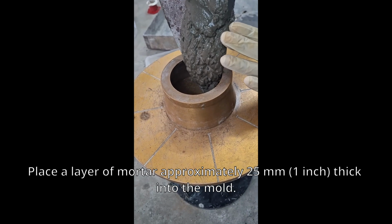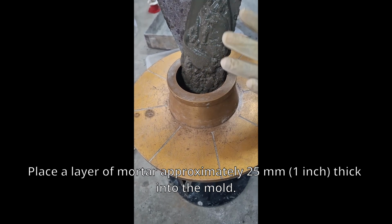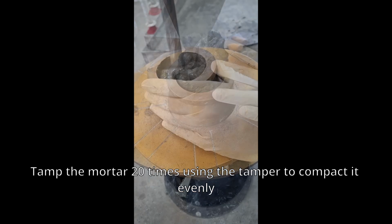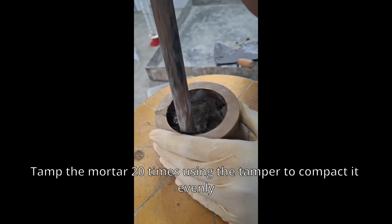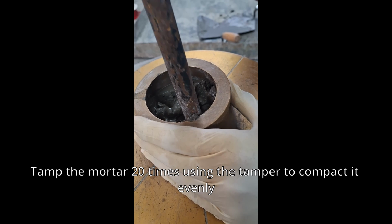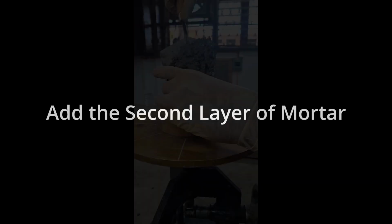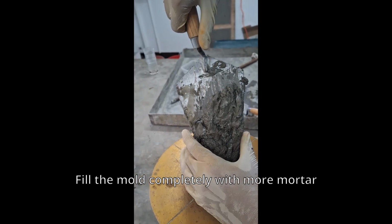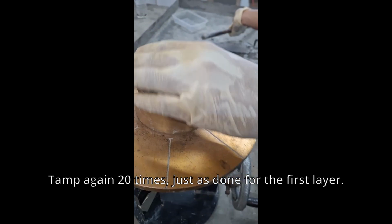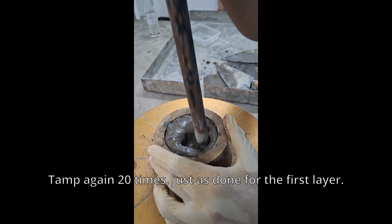Add the first layer of mortar. Place a layer of mortar approximately 25 mm or 1 inch thick into the mold, and then tamp the mortar 20 times using the tamper to compact it evenly. Next step is add the second layer of mortar. Fill the mold completely with more mortar, and again tamp 20 times just as done for the first layer.